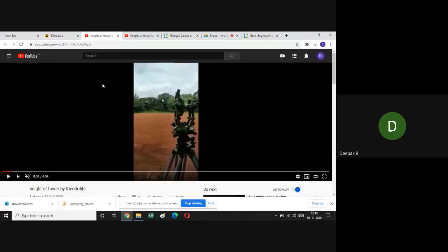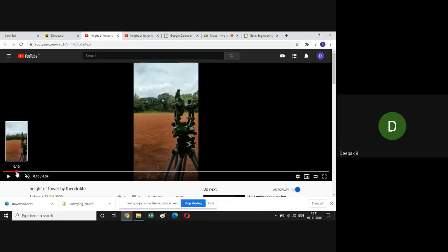So as you know, this is the theodolite that you have. From the first experiment itself, we saw how to take horizontal angles from this horizontal plate. There are two verniers, A and B, and you take the average of them to get the actual horizontal angle. Similarly, there is a vertical circle, which is also graduated, with a C vernier and a D vernier. You take both and find the average so that you can get the vertical angle.